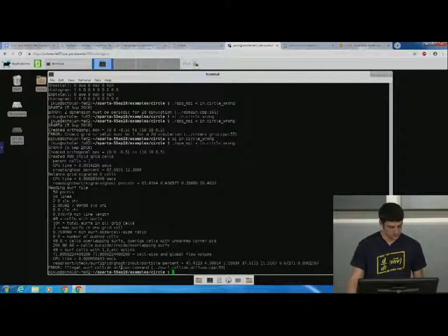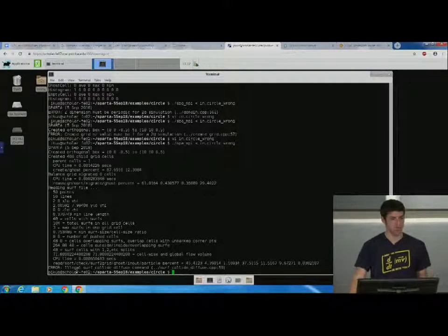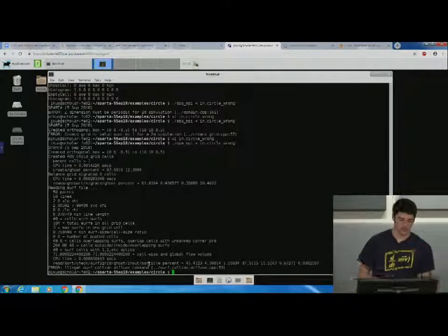Yeah. And basically illegal. And this one is much more generic, right? It doesn't tell you specifically what's wrong. It just says illegal surf collide diffuse command. So this one doesn't tell you what's wrong. So you have to look at the file and probably look at the manual at that point to see the syntax and line it up. So it's all out there, well explained, but it'll still take a bit of digging.